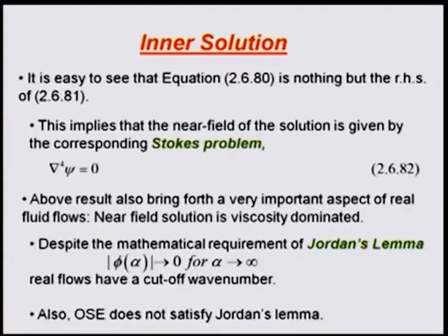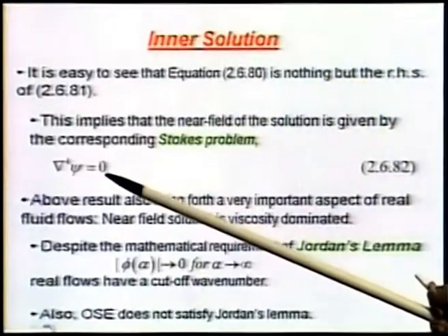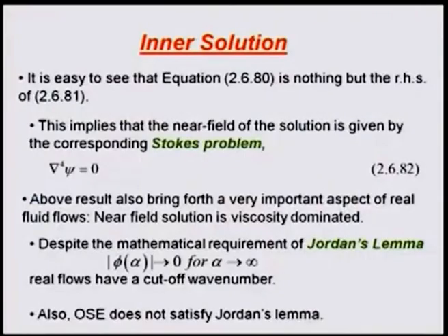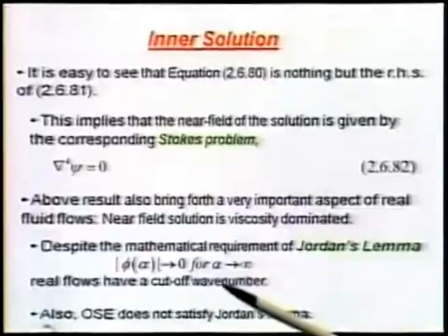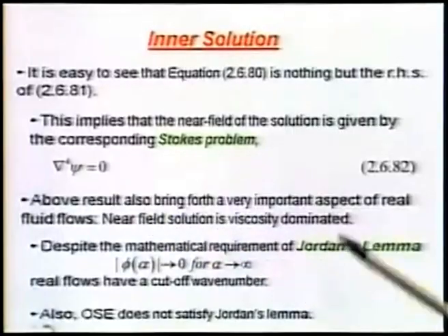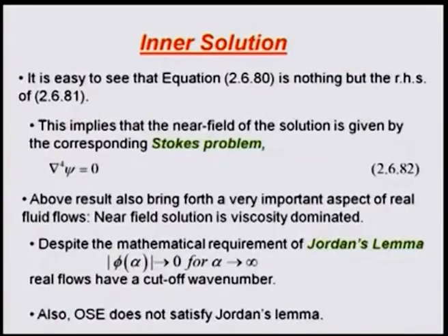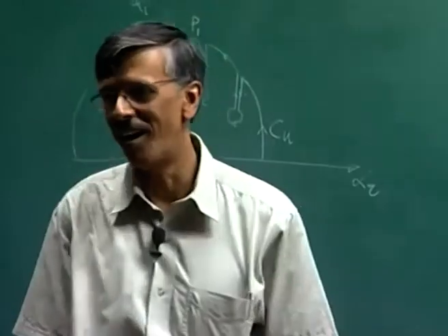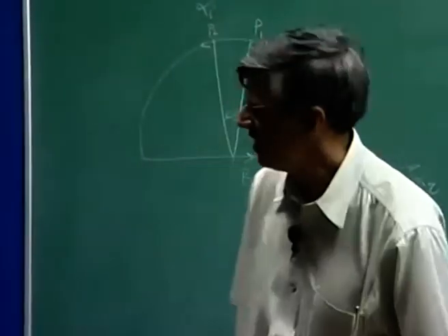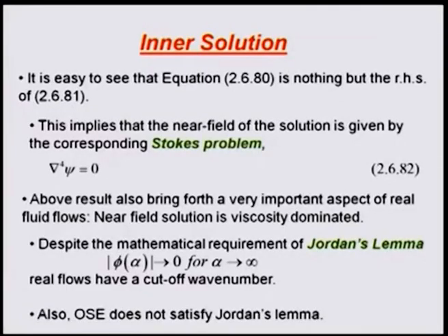This is all coming from what we have done, that singular perturbation analysis. The inner solution reduces to the Stokes problem, that is del 4 psi equal to 0. So near field solution is viscosity dominated because Re goes to 0.